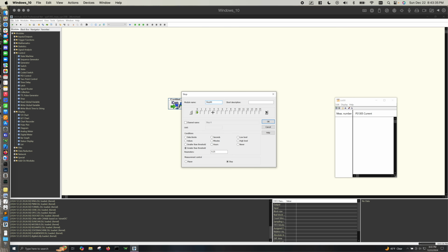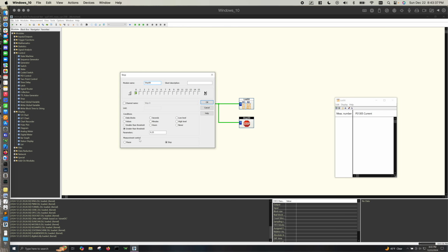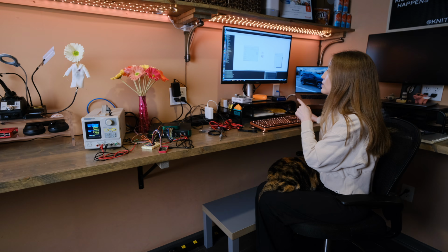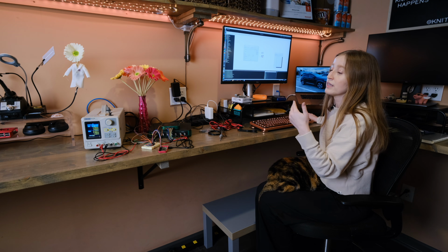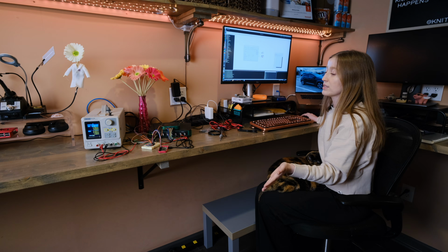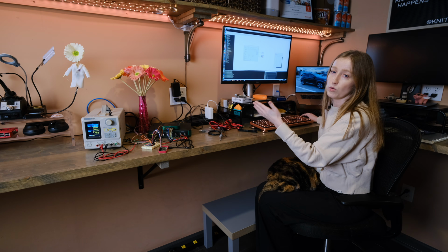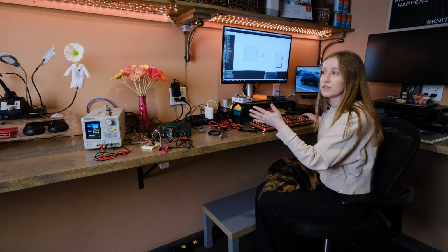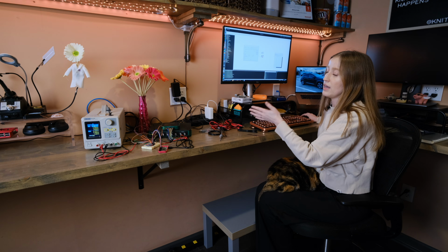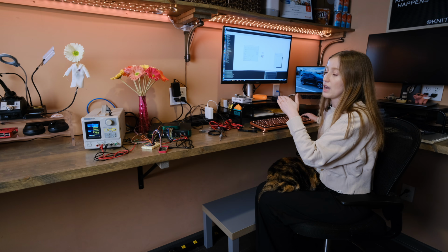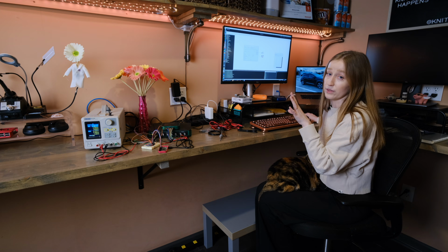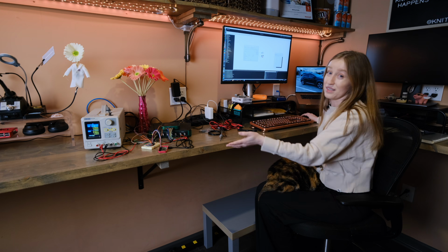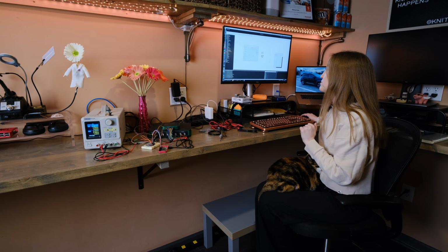But this time the stop condition is when I hit a parameter where the measured current is greater than 0.25 amps. Because I found out by trial and error that once the Raspberry Pi has gone above 0.25 amps for a moment, at least several measurements, it might settle back down below that, but once it goes past that threshold, that's when I know the Wi-Fi is up and running and ready for me to SSH into the Raspberry Pi.